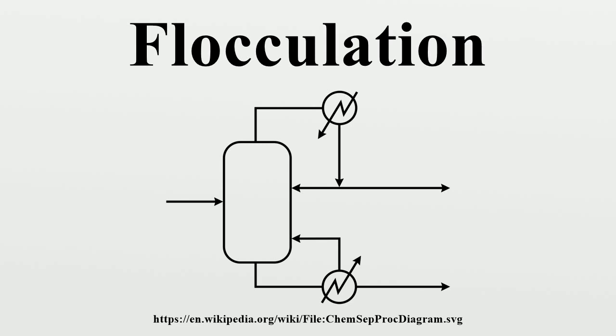According to the Encyclopedic Dictionary of Polymers, deflocculation is a state or condition of a dispersion of a solid in a liquid in which each solid particle remains independent and unassociated with adjacent particles. A deflocculated suspension shows zero or very low yield value. Deflocculation can be a problem in wastewater treatment plants as it commonly causes sludge settling problems and deterioration of the effluent quality.